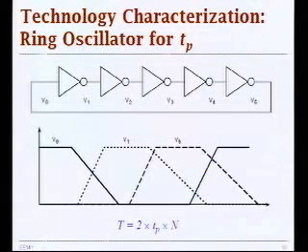And if you actually do a little thought experiment, you can put this ring oscillator together, and then you can see for the half period how many low to highs and high to lows you have. For the other half, how many you have. And you will exactly end up with this number, that you have 2 times the average propagation delay times the number of stages. And this was a useful metric to evaluate the capability of a technology,